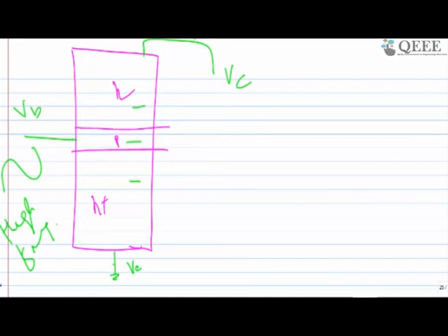So I am saying first a parasitic here, another parasitic here. So base to emitter is called junction capacitor. These blue colored ones are parasitic capacitances, and they are activated because you are at high frequency and there are different plates I am seeing. And between base and collector I am seeing one more capacitance which is called C mu.